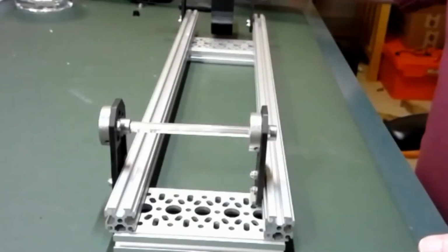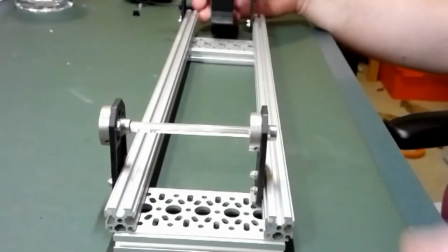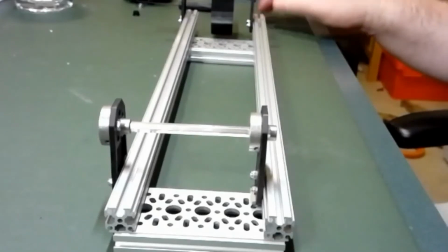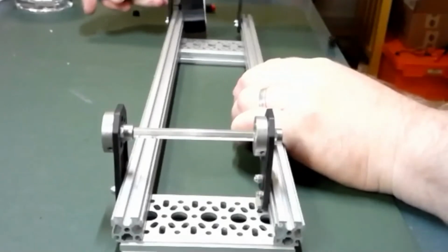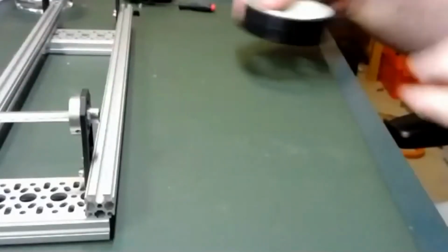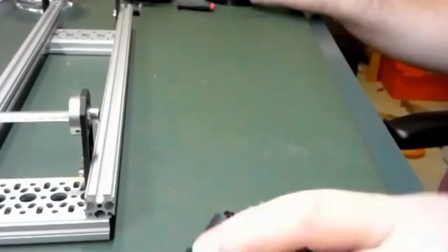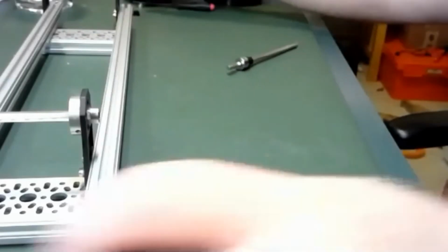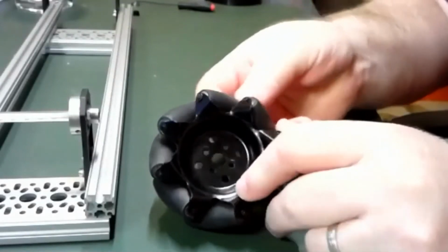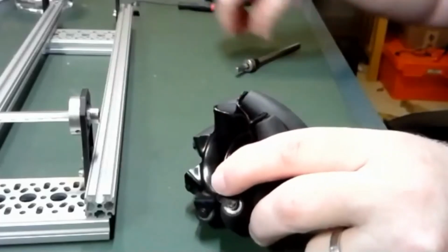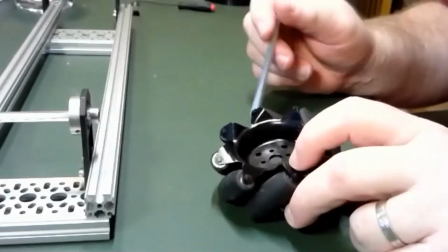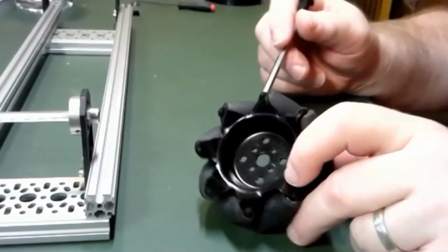Now the part that becomes tricky is how you get the bearings on the Mecanum wheels. For the Mecanum wheels that 7172 uses, that's pretty easy because we used Nexus wheels in previous seasons, and you can do it with the goBILDA wheels. We create our own custom hubs for those wheels that can contain the bearings. But the REV Mecanum wheels posed a challenge because the mounting points are inside the wheel, down in this well, and there's not a good place to attach a bearing to go around a shaft. So we ended up making a 3D printed piece to do it.